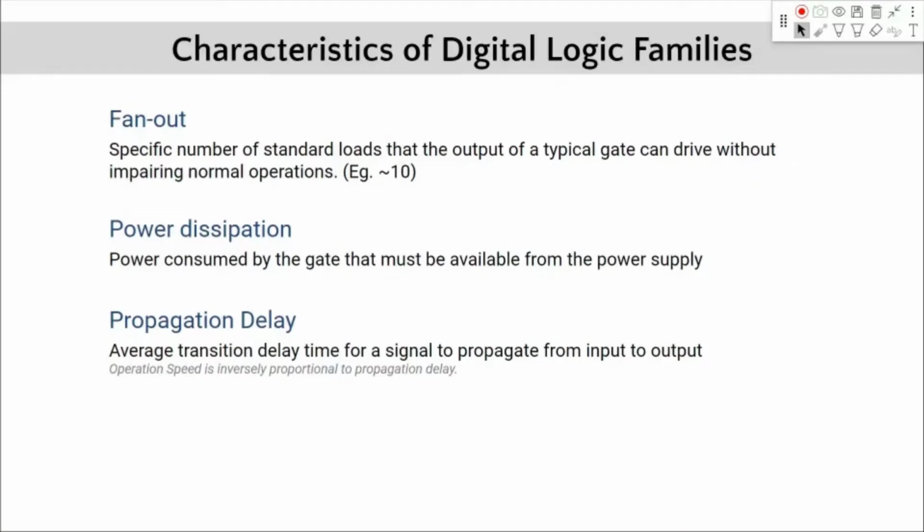In a logic family that we want to use, we want the propagation delay to be as low as possible. So if I wanted very high speed operation, which logic family would I use? Emitter coupled logic, ECL. And I know that there the transition delay is in nanoseconds.